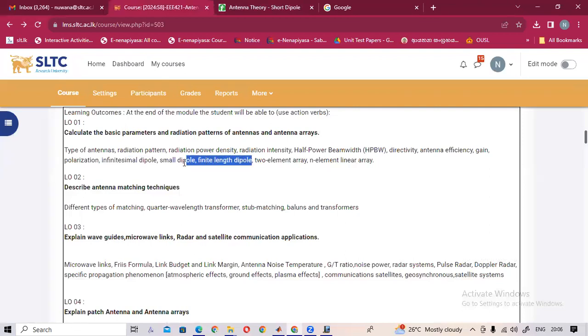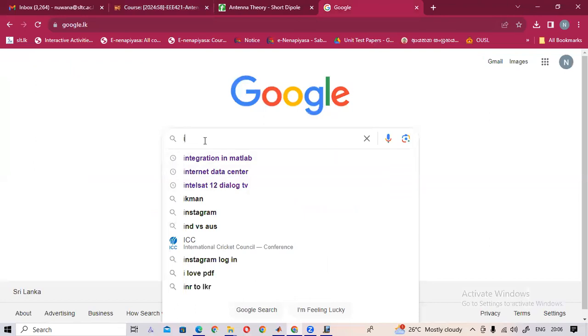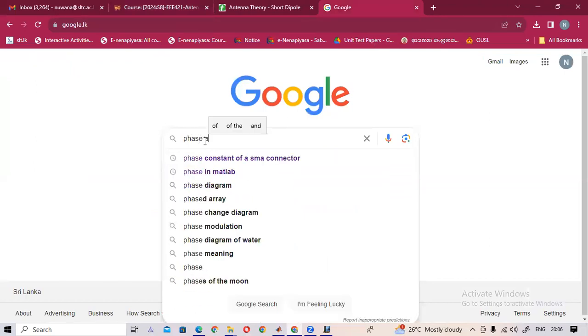So these are the finite dipole antenna. And the array antenna, in my lecture, I have just introduced what the array antenna is. That means we are using more than one radiation element for transmitting, so we call them array antenna. Using the array, we can send a signal to a specific direction. I am hoping to do the phase array antenna, that is one type of array antenna.